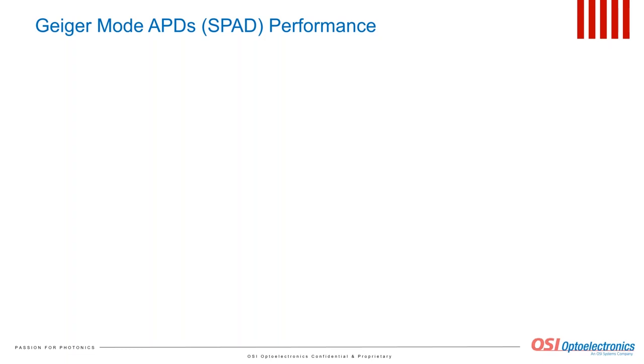The simplest way to quench the avalanche is to add a quenching resistor in series with the APD. In this case, after starting the avalanche, the resistance of the diode drops dramatically, and the current flow through the quenching resistor causes a voltage drop on the resistor, thereby decreasing the bias across the APD. This stops the avalanche.